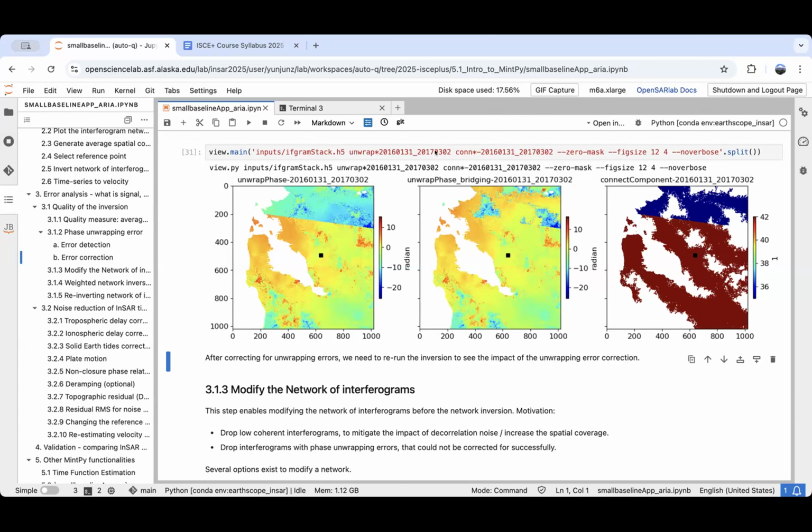Then can we just take the affected area only? Like, for example, in case of a landslide. Yeah, if your goal is localized, I think you can focus on that scene, place a reference point close by, just not on the landslide itself, of course. So you need some area outside of the moving terrain to be able to form a reference. But otherwise, that's what I would do. There's no huge point in processing large areas that you aren't really interested in.